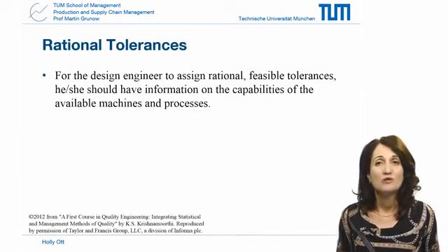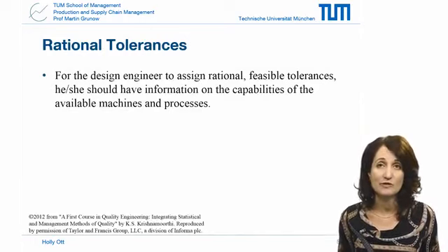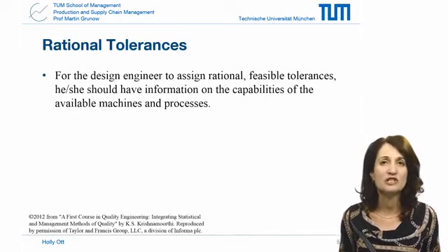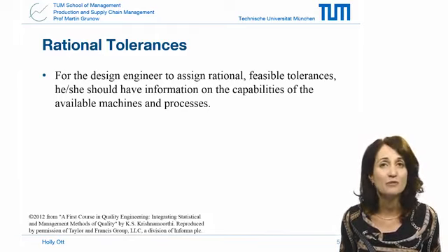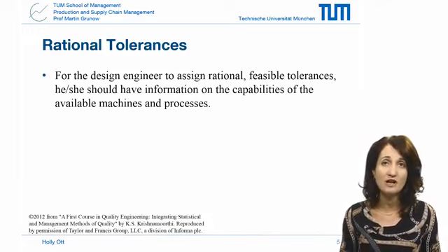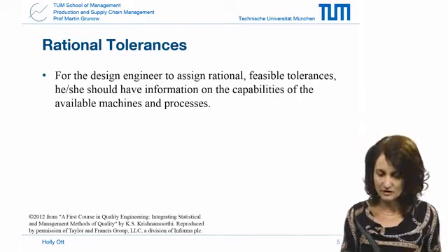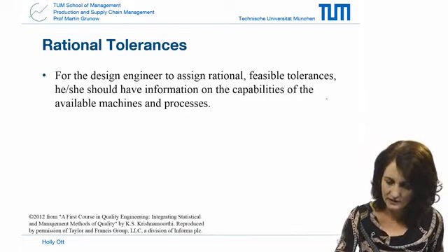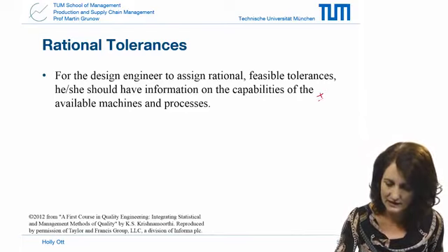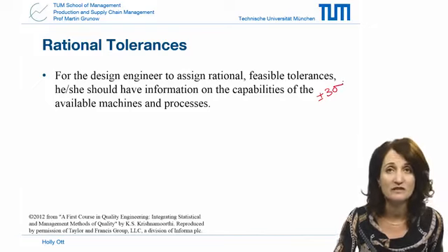Now, these tolerances will be adequate and appropriate to use for a new product if the production machinery used for producing this characteristic has the same capability as those assumed in attaining the standard tolerances. So we were just talking about this plus or minus 3 standard deviations.